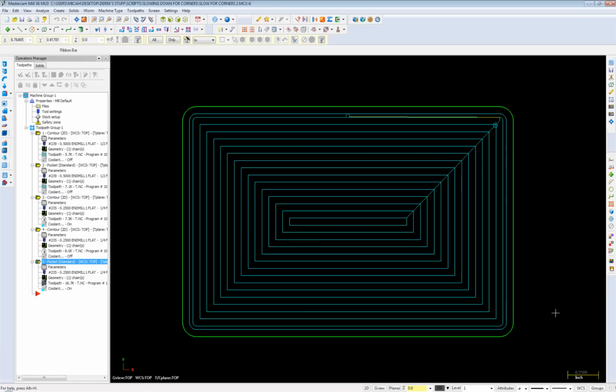Right. It could be that the controller has been set by the manufacturer to hold really tight tolerances, perhaps tighter than you need, so it's accelerating and decelerating more than it needs to. Some of the machines like Matsuuras, I'm sure Mike knows the same thing, have a couple of different settings for the high speed look ahead, a fine or a heavier type. I know that in the Matsuuras and I think the Toyotas too. You know what I'm talking about, Mike?